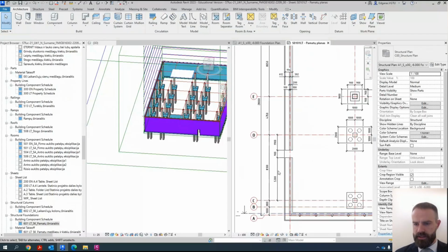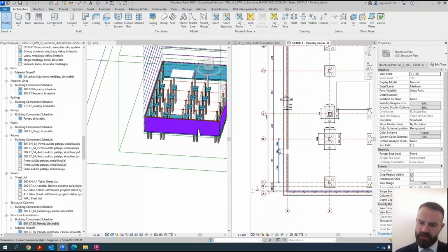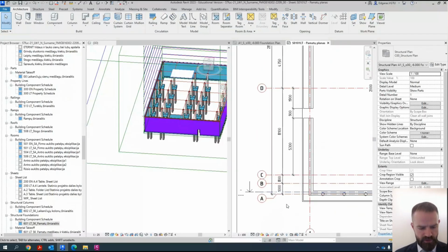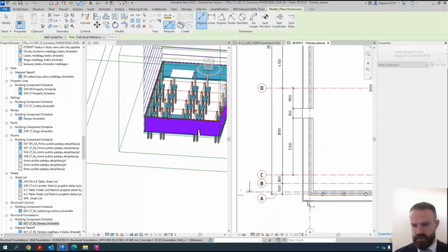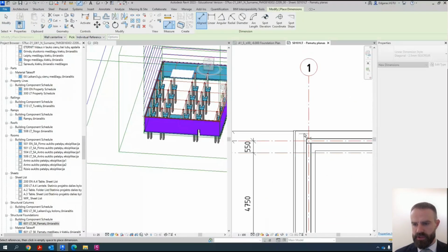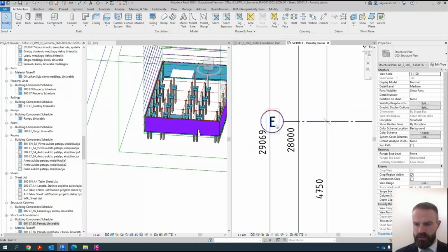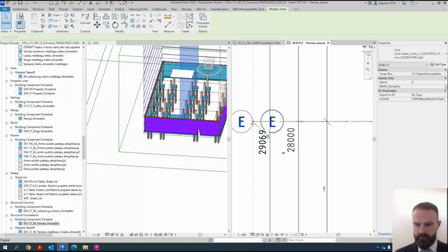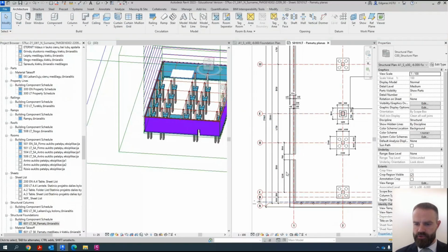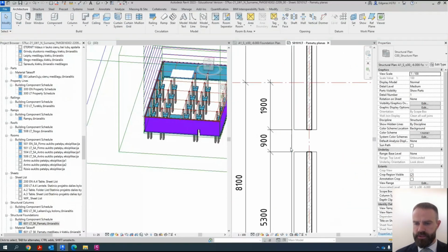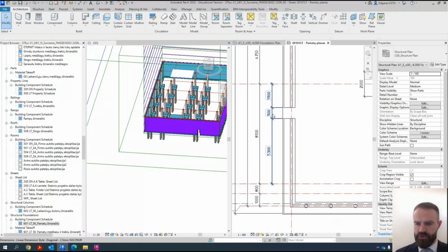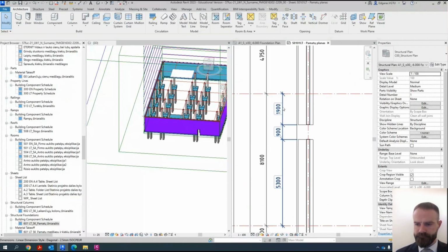And in this case, I can have a lot of levels, and one of dimensions was deleted because my structure was changed, and I just need to recreate the dimension. And now my dimensions have additional level, which explains in which location I have the opening.